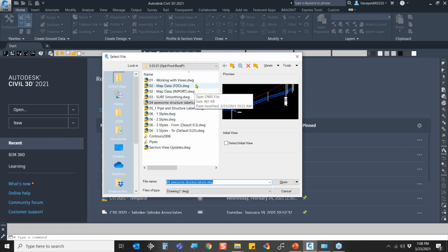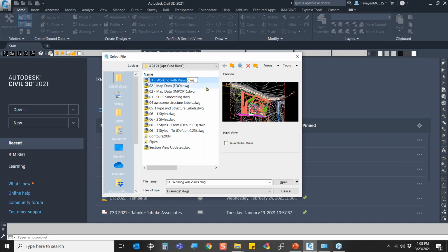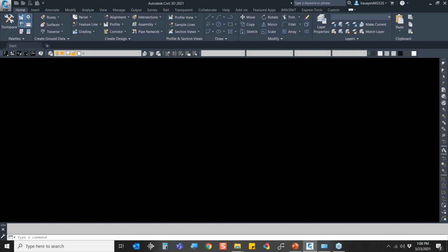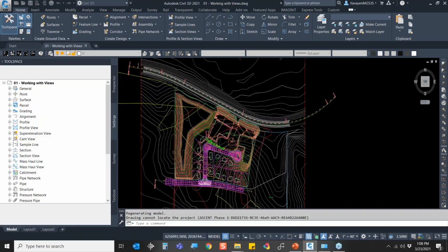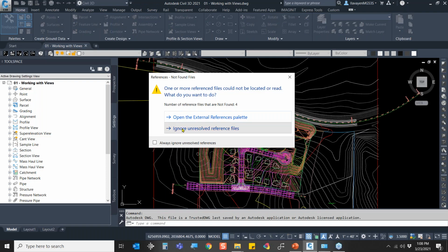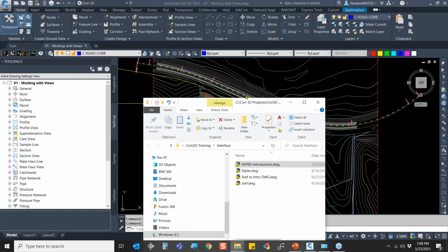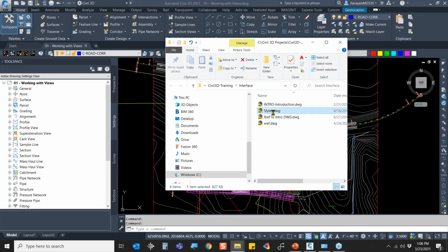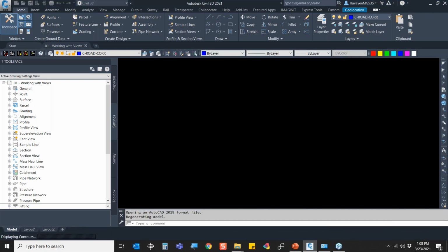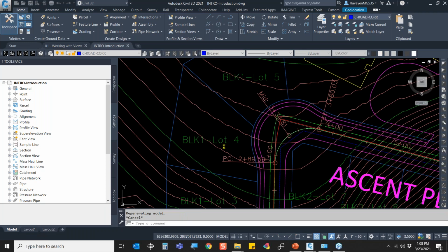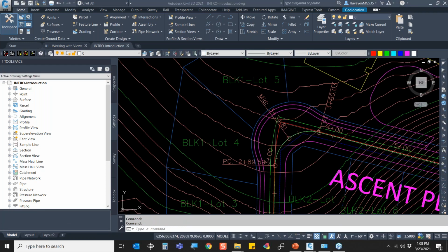That's really what I would prefer you to do, is go out there and actually open a drawing in that fashion. But what we could do here is drag and drop to a command line. So let me just go ahead and open a drawing so we have the command line readily available. And what I would like to show off here is if we happen to have other drawings, what I can do is take them and either drag and drop them into my AutoCAD session, which will run as an insert, or if I drag and drop into the command line, it then performs an open command. So I like doing that because it really feeds into what we're typically working with.